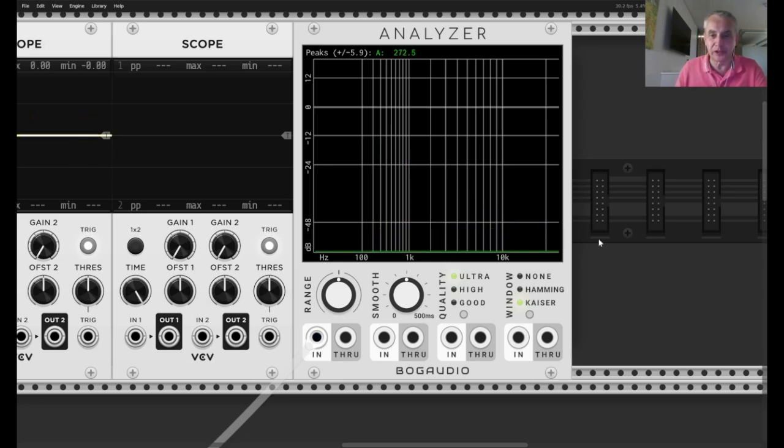The ramp should continue over here, but because the sampling rate is too low, those higher frequencies are not sampled back correctly and mimic themselves or are aliasing themselves. They're an alias of a different frequency and they come back as lower frequencies, sometimes in the audible range. And that's why you sometimes see these jumps in pitch, or they look like jumps in pitch.